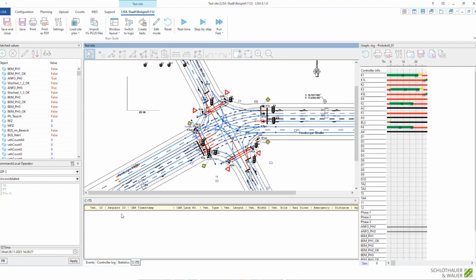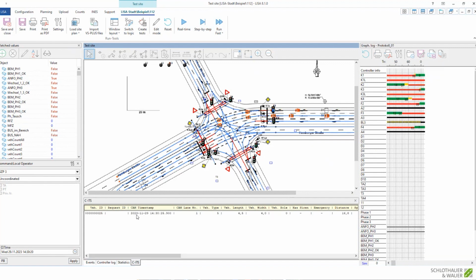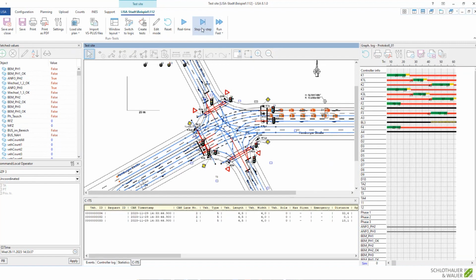instantly clear. Now I have much less messages here in my vehicle buffer, although I still have this big number of vehicles, which also leads to the answer of a question that nobody has asked yet. Of course, with this method and with these tools, I can have a control that is using both static detectors and CAM messages, because in my logic, it is just a different function. I can get the information from the static detector and as well from the CAM messages, and then do something that is taking into account both types of information, which is, I think, a pretty cool feature.